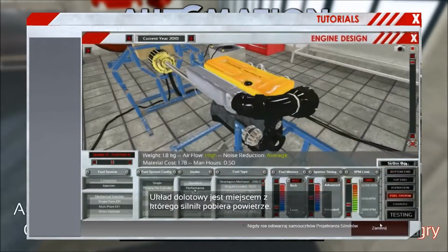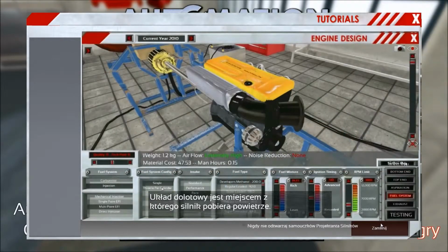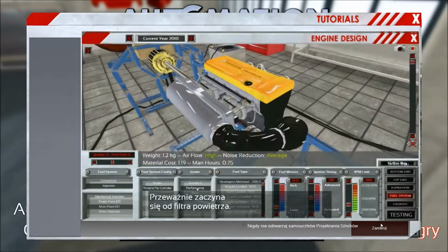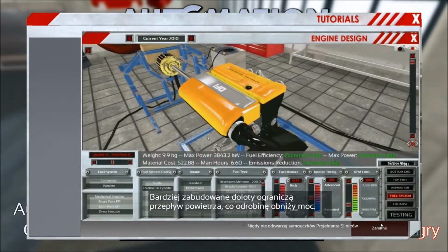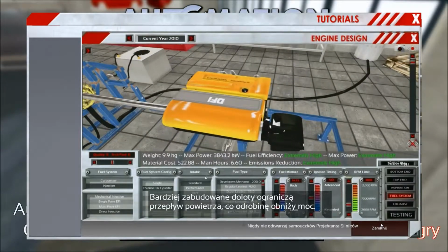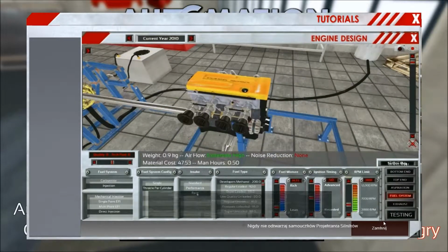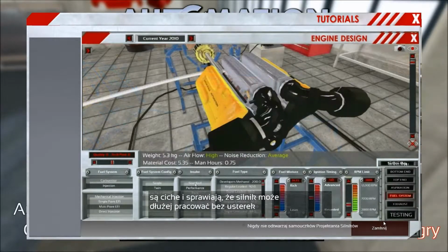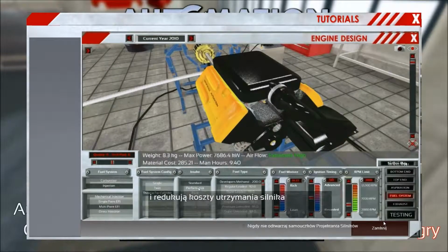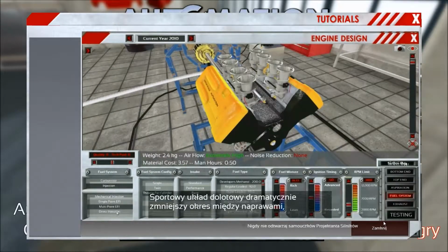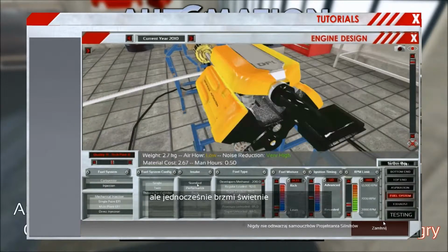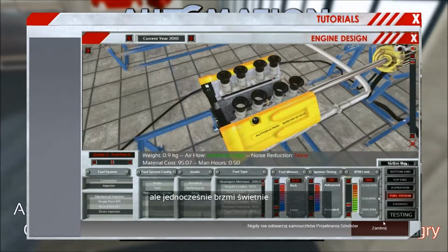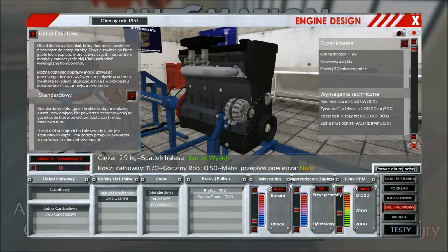An air intake is the point from which the engine is supplied with air. This air is usually drawn through a filter first. More enclosed intakes will restrict airflow and thus make a little less power. On the other hand, they are quieter and will make the engine more reliable with reduced service costs. The race intake will dramatically decrease the engine's service life, but it will both sound fantastic and not restrict.